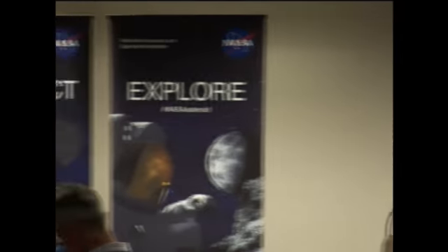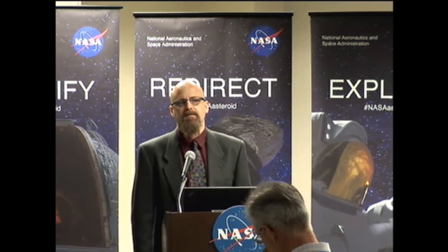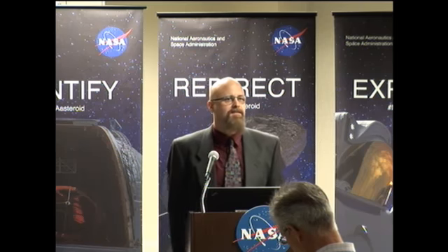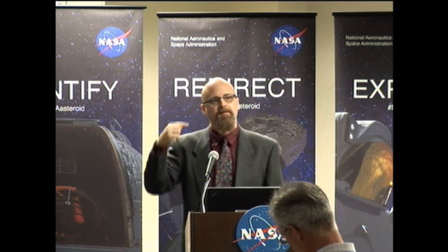I haven't thought a lot about it in our modeling. We went pretty straightforward with that, but I really don't see that as much of an issue. It's really just a moment arm thing. It's still going to spin, and if we're coming off the side and there's no moment arm because we're just wrapping around this way, it would be really improbable that you would see that condition purely. If it was pure spin, we'd put ourselves properly. If it was a combined thing, we'd take out most of it in one axis, and then there'd be a little bit of a moment arm issue in the other axes, but I think it would despin. I think that would be a great simulation effort to look into fairly soon.